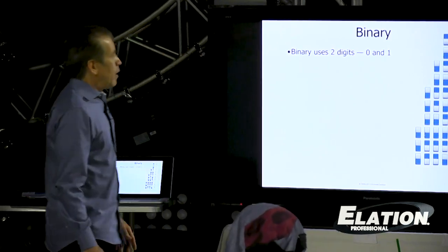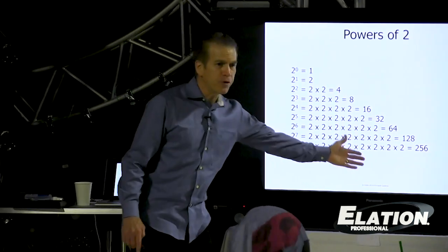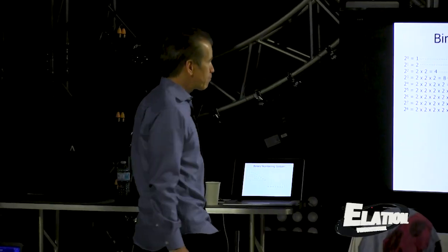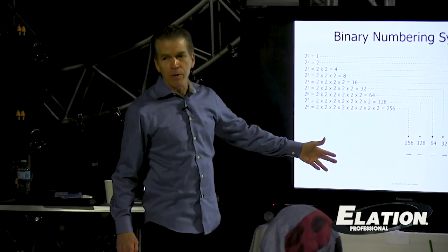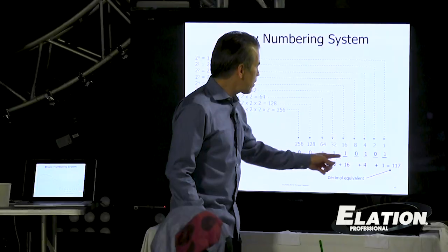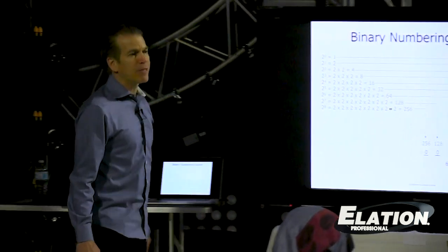Powers of 2. So you'll see those a lot with digital electronics. So this would be the 1's column, the 2's column, the 4's column, and the 8's column, right? And these are all powers of 2. The next one would be 512, 1024, and so on, right? So if I wanted to convert a binary number to decimal, I could look in the column, and if there's a 1 there, then I would add that power of 2. So in this case, this binary number, which is 1110101, converts to the decimal number 117. Okay?